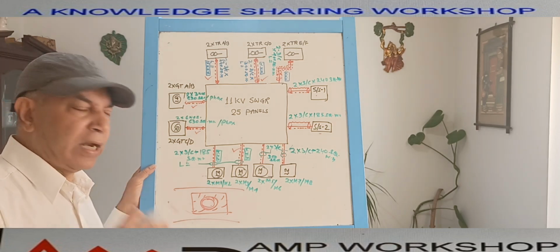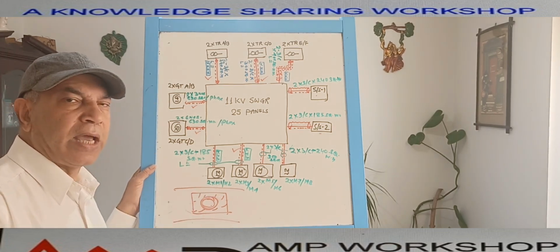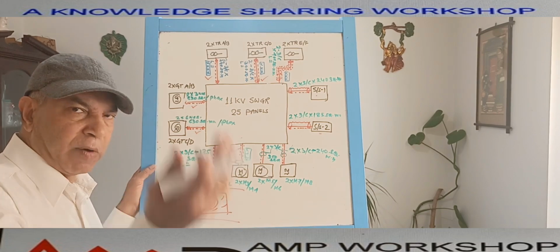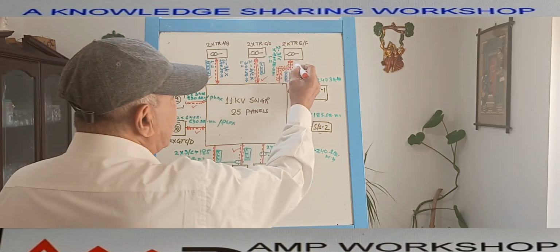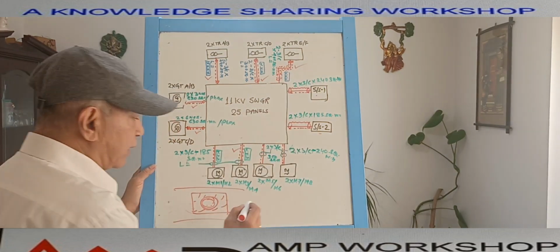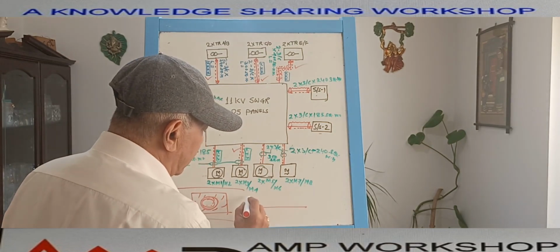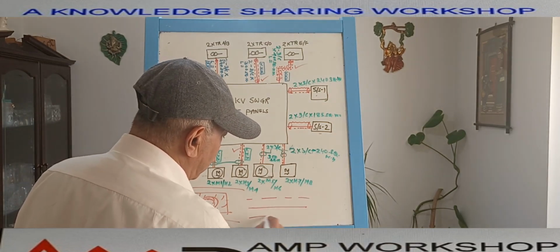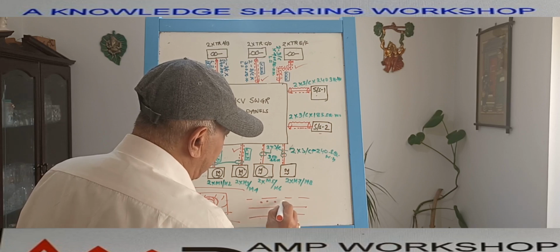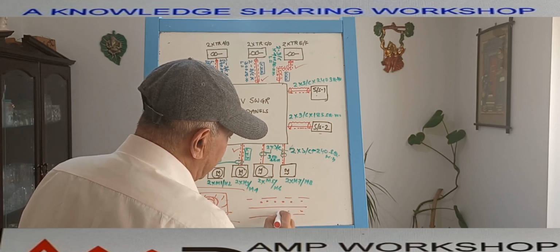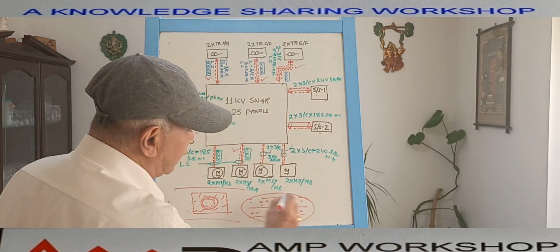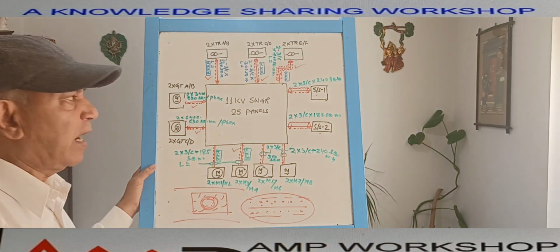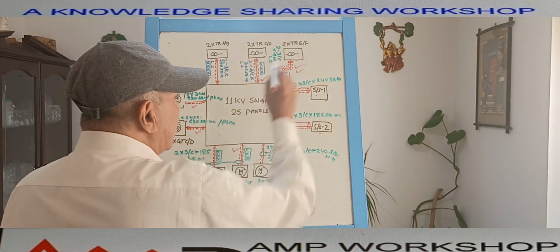When the oil field is on the land, normally we put the cable in this type of arrangement to protect it from the environment. This is a duct bank. Suppose this is one of the cables we have considered laid in a duct bank. How is that symbol shown? Top is soil, bottom is soil, and inside these are the duct bank. This is the symbol of the concrete. So this symbol means this cable is laid in a duct bank.